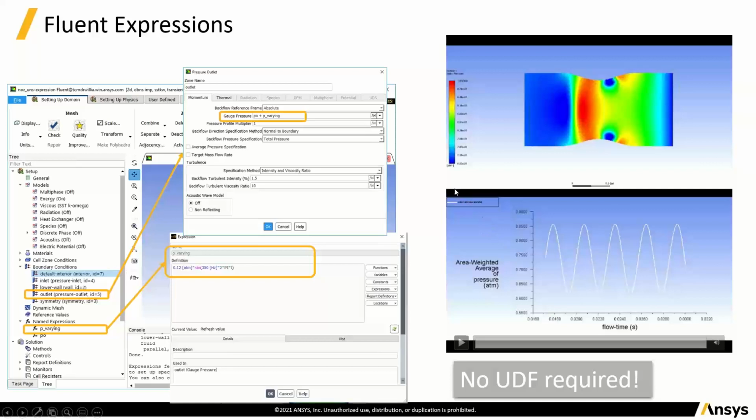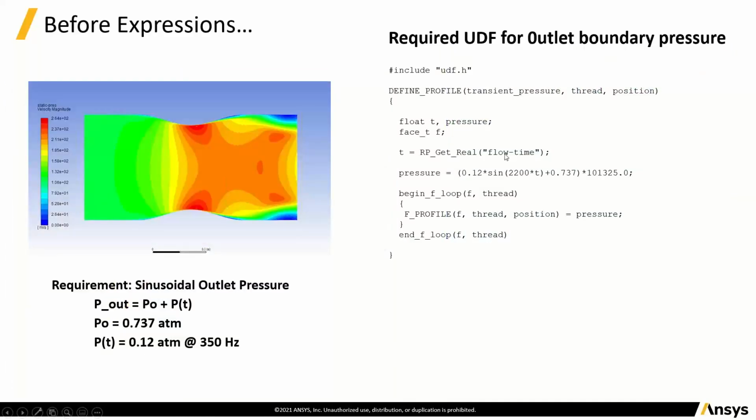The nice thing about this is there's a lot of diagnostics we can do on the way. We can actually plot this as a function of time before we even start to make sure that all our units and things have come together. Also, we can make sure that we've got consistent units and things, which if we just go back to that UDF, it's up to us to make sure this is all giving us units that are in the SI system.